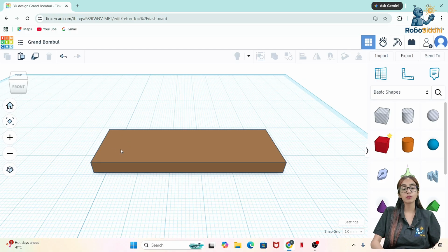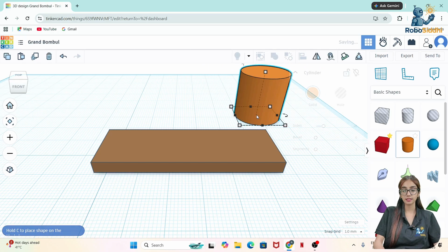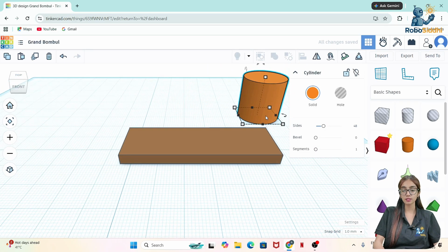which is a hole, which is a holder for the keychain, right? A holder for the key or for any upholding thing it will carry, right? So for making a hole over here, I just need to drag a cylinder over here. Okay, so here is my cylinder, and what I have to do is, again,